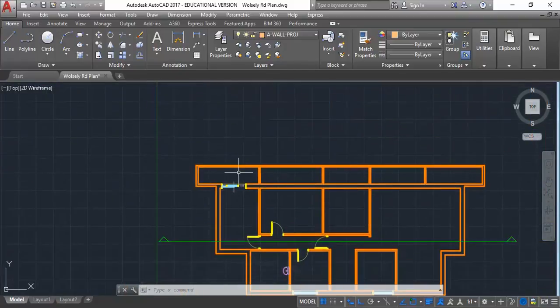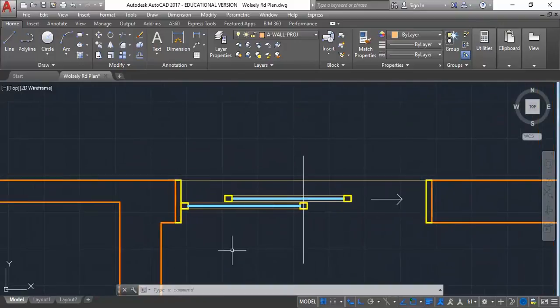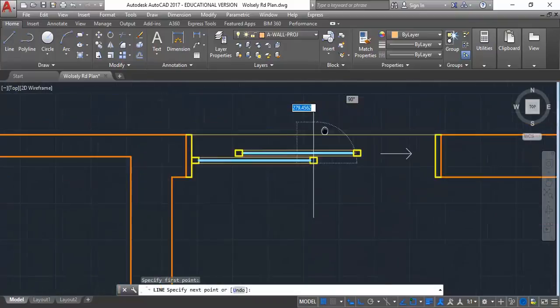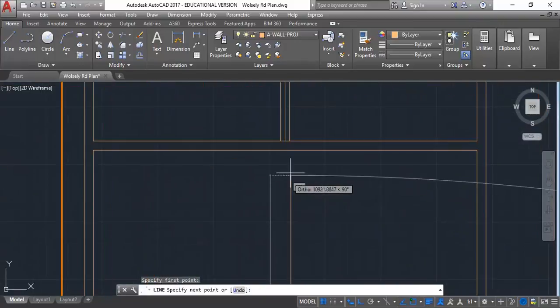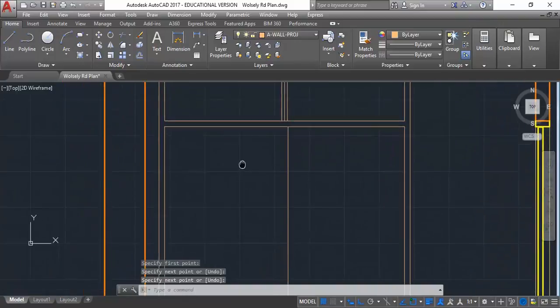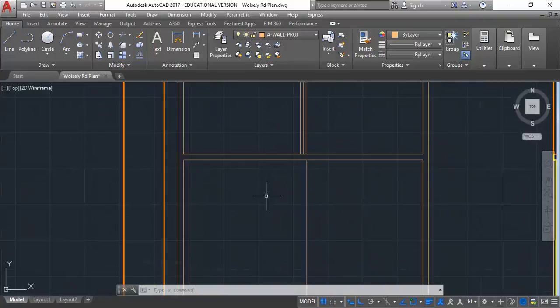So then the door, you can set out in the elevation, but we've done it all in plan, so it's sometimes easier just to come back and draw the lines from here, project up to the frame. So that's one side of the door, and then I've made them all 40, so I can offset 40mm.